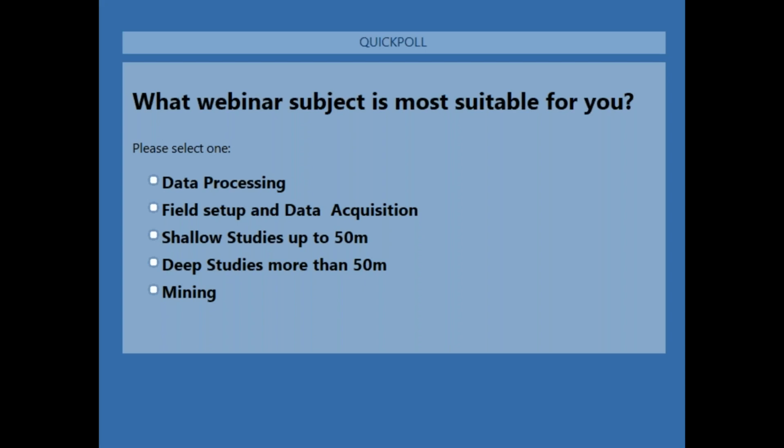Contact resistance can be lowered on land studies by putting salted water, or you can also use a bentonite solution, and you can put more than one stainless steel electrode, and dig the ground a little bit and pour more water. Try to reduce the contact resistance on land if you have a high contact resistance, especially if you're doing mining IP or resistive IP studies.